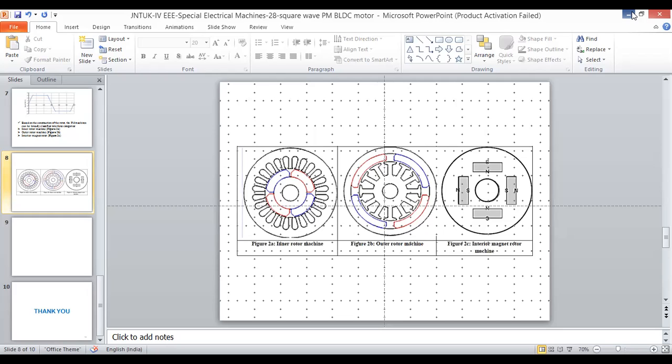In practice, most of the motors are inner rotor machines only. The inner part has the permanent magnets, and over those permanent magnets, on the outer part, we place the stator slots and stator winding. Whenever the flux produced by the permanent magnets cuts the armature conductors, the stator MMF can be produced, and also an EMF is produced within the stator, and then the torque.